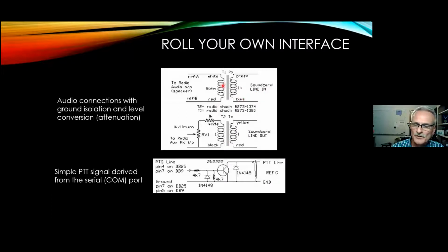The transformers in use here, and by the way, this circuit came off the internet from way back when there was a Radio Shack and you could go down and buy parts there. These transformers are put in here to isolate the ground between the radio and the computer. And I'm going to talk about that in a little bit. But this is providing me with my transmit audio and my receive audio. And then down here is the push-to-talk circuit.